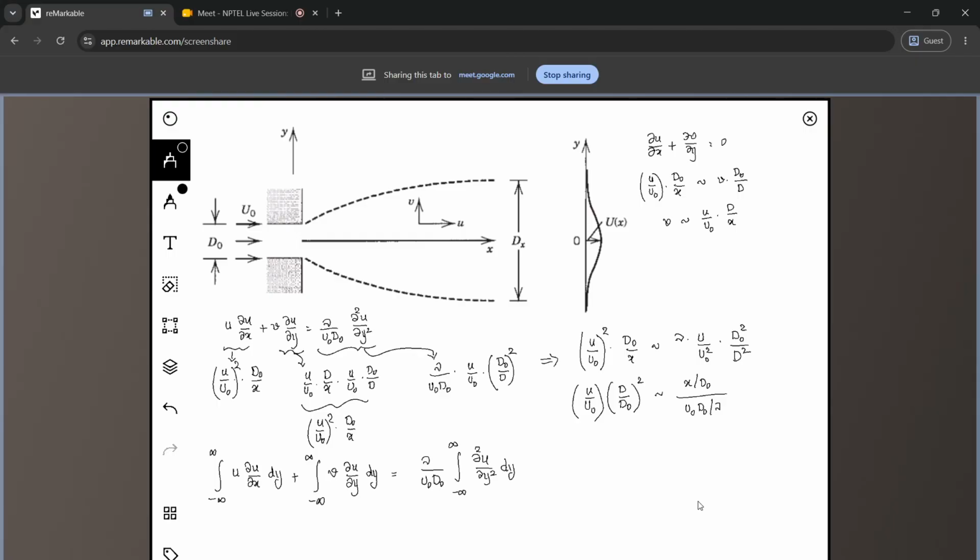Are you able to get some equation? Or maybe we can do it term by term. So let's say we'll start with one term. The first term we can do just like what we did in the boundary layer equation. So this term will essentially boil down to something like, just take the u inside, so put half times del u square by del x, dy. For the second term, you can apply integration by parts, which will give me v times u